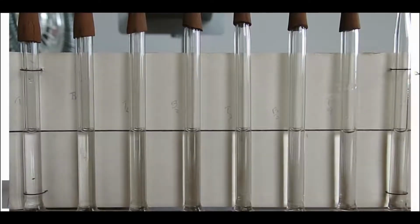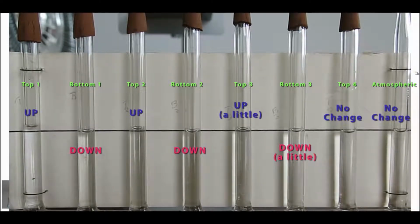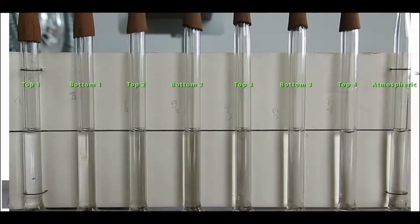And what we're going to do, let's put this in a wind tunnel. It's actually not a wind tunnel, it's a fan. But what you can see is the pressure is changing at different positions along the airfoil. At the front, the top one, two, and three, you can see that the pressure is lower, and consequently the manometer lifts up. And on the bottom, the pressure is higher, and consequently those move down. And closer to the end, there's not really much of a change.